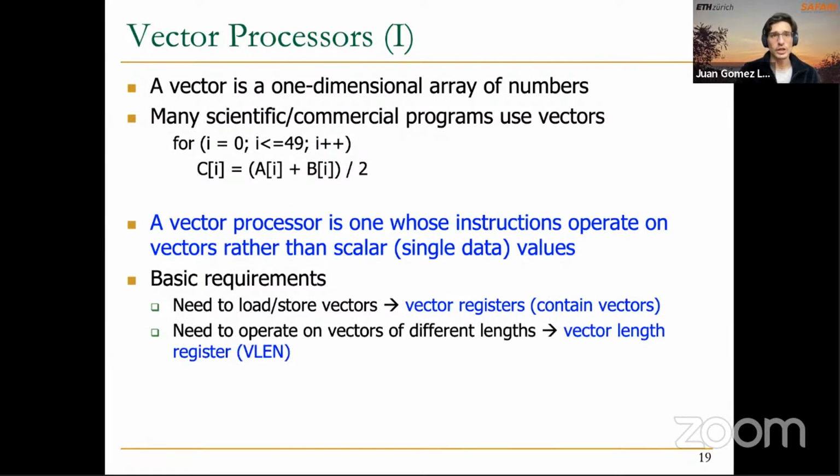We also need to define what's the length of the vector, because that's probably going to be a limitation that the hardware itself is going to impose. How many processing elements you have, how many processing elements you can use at the same time. If you think about an array processor, in the example we saw before, we had four processing elements, that could be our vector length, right? And we would be executing vector instructions for every 4 elements.